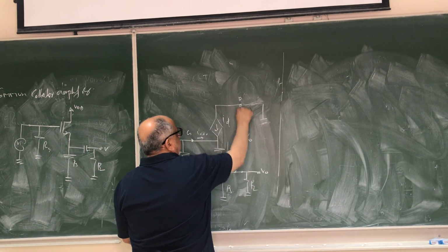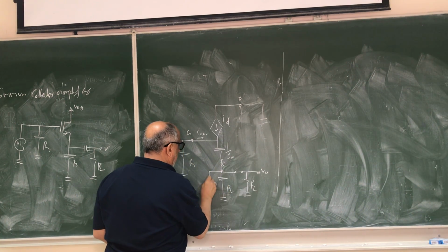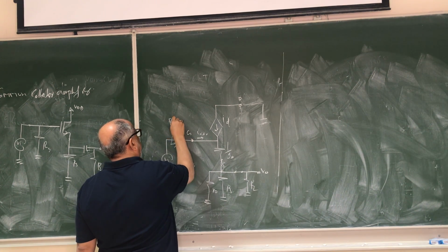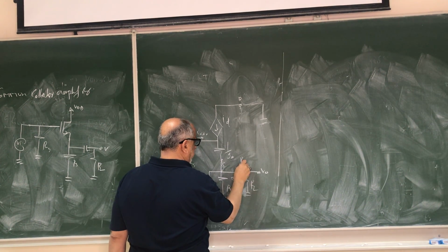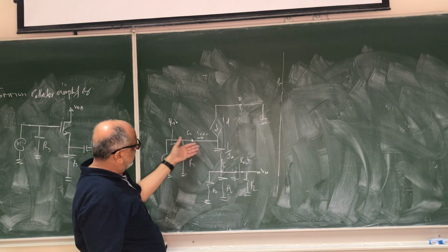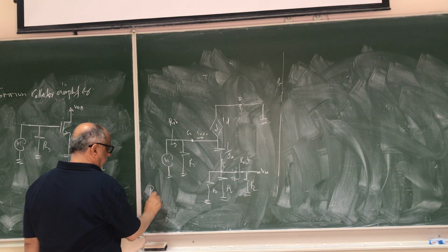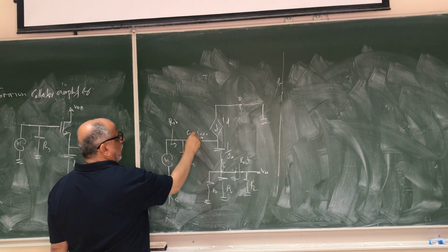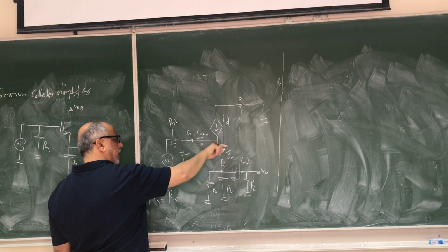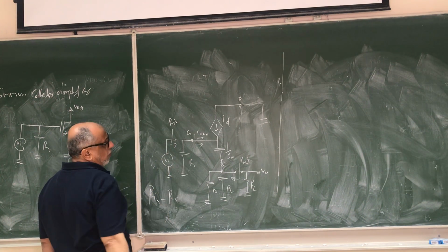So this resistance here, we can turn it down, as we have done with the BJT, so we can connect it here as RO. Now the input resistance is this, Rin, the output resistance is here, Rout. Remember, the gate current is 0, so what we can see here is an open circuit, there's nothing there. So Rin is RG. Why? Because the resistance here is infinity. Volt divided by current, the current is 0, so it is infinity. So we cannot see anything here. Infinite input resistance in this direction. So the input resistance of this amplifier is RG only.